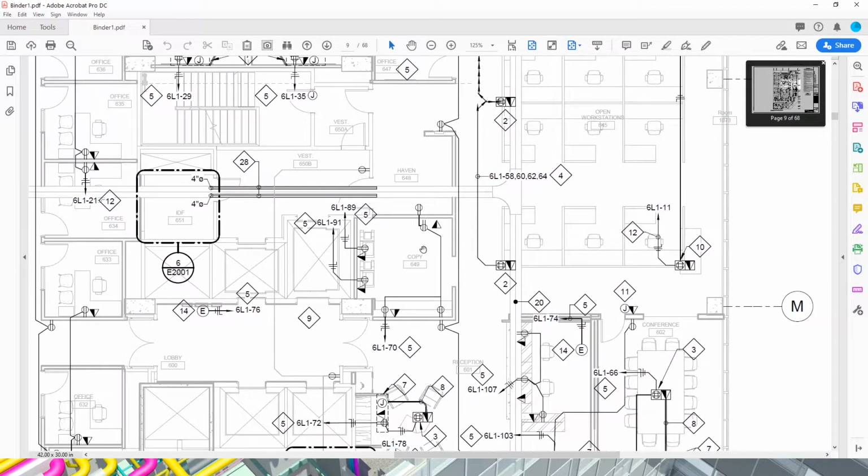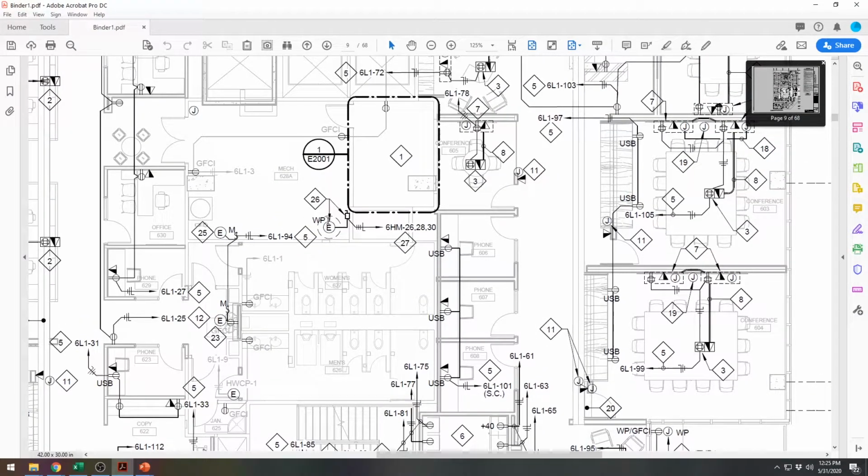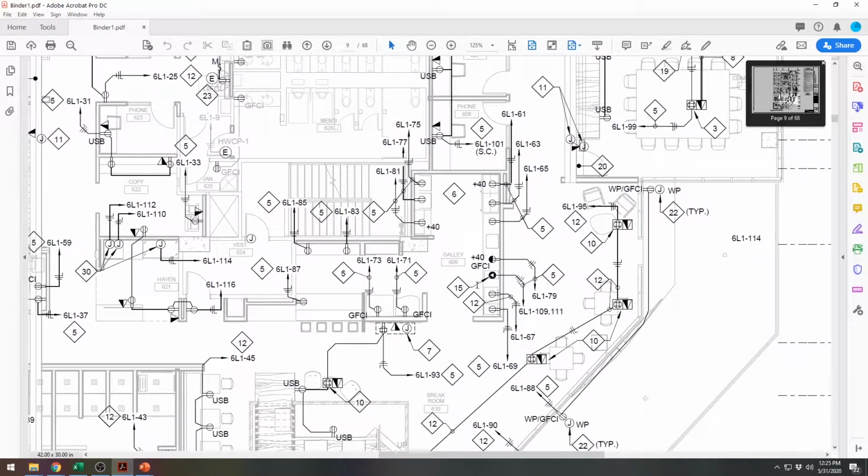Printers. So essentially, we have to coordinate with the architect and the client what equipment needs to go in. Do they need special requirements? We have to power all of plumbing. So this is a water heater, and so we have to essentially get with plumbing and mechanical and the architect and the client and make sure everything is powered and there's enough space electrically for everything. Kitchens, that's a big one that needs a lot of coordination. Coffee makers, ice machines, things like that require a lot of power.